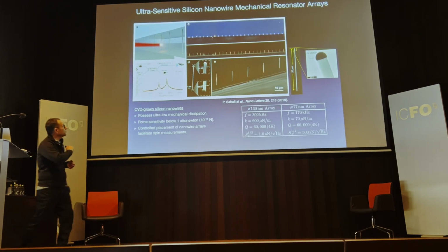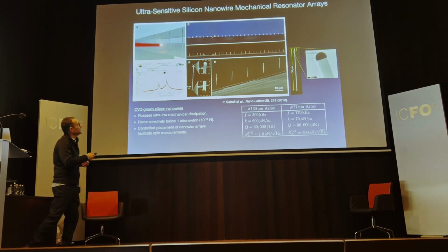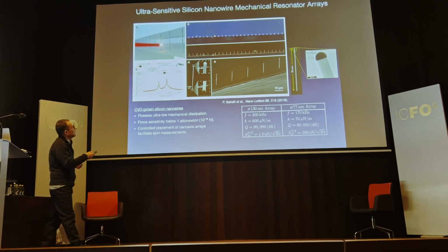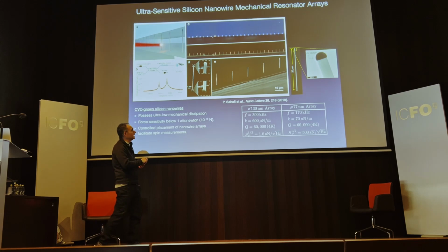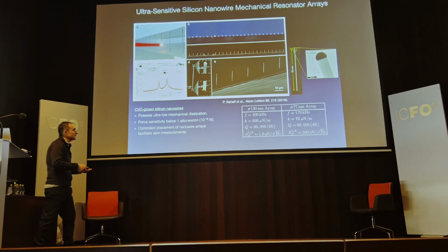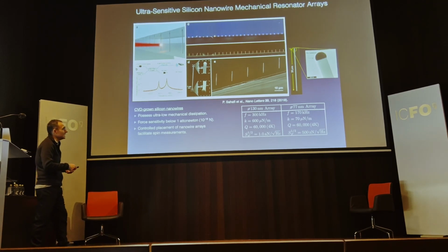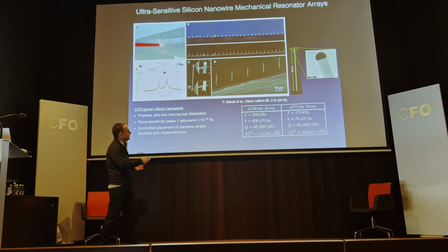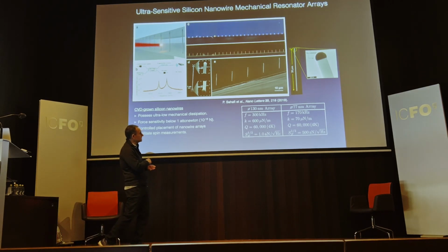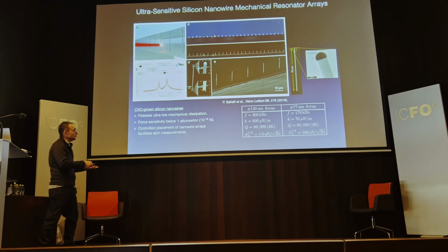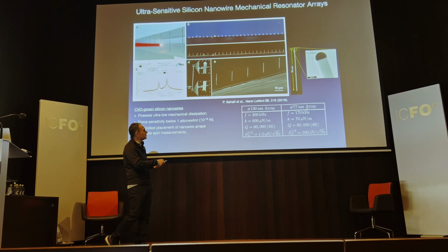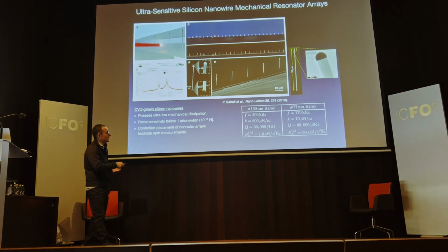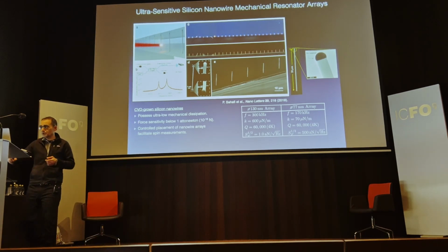And we also make our own silicon nanowires, and we make them in an array form. These are 20 micron long, typically 100 nanometer diameter silicon nanowires. Here are 2 batches that we studied. They have very reproducible characteristics, quality factors of about 60,000. This is 130 nanometer arrays, spring constants of 600 micronewtons per meter, 300 kilohertz, 1 attonewton per root hertz at 4K. This one is slightly softer, has better force sensitivity of 500 zeptonewtons per root hertz.